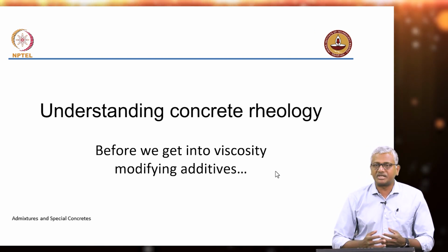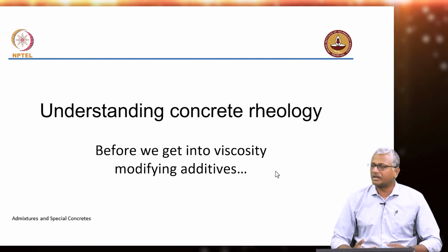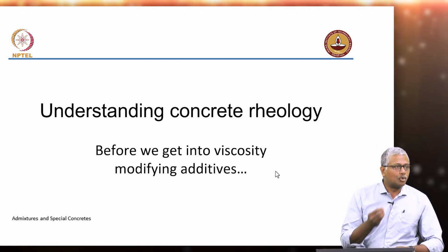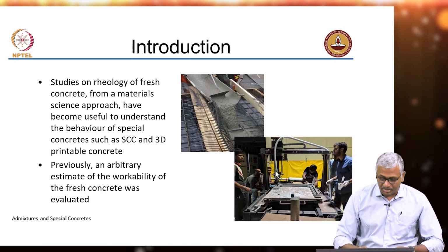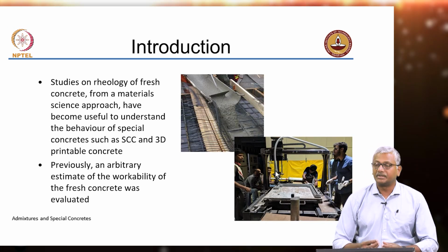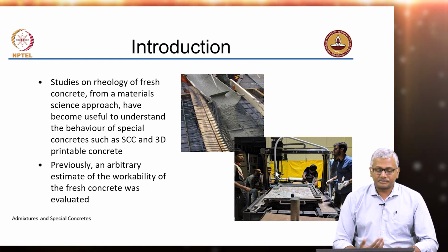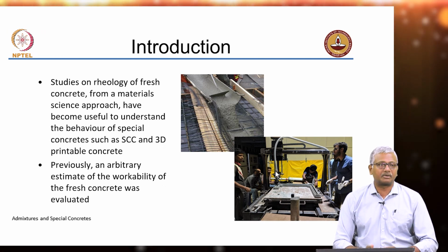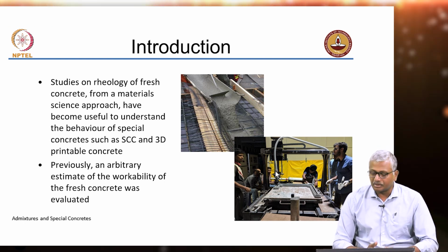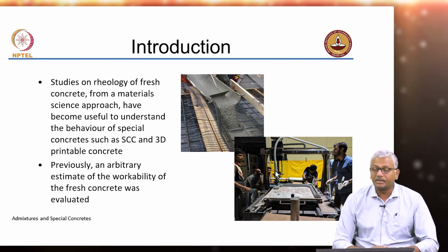So far we talked generally about slump or other workability test methods, but that's not really capturing the entire flow behavior of concrete. When we talk about rheology, we are trying to understand the entire flow behavior, not just the workability. So, as I said, when we come to special concretes, it's not just the workability, but the actual rheology that controls how these concretes actually work.